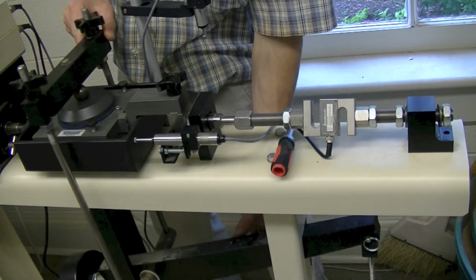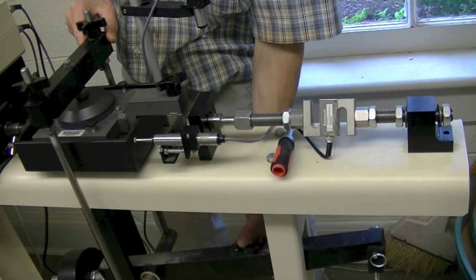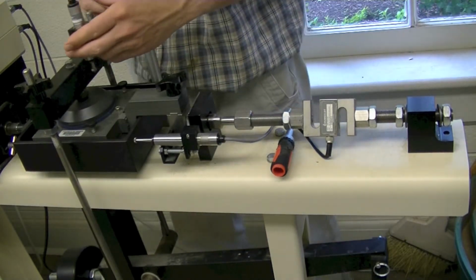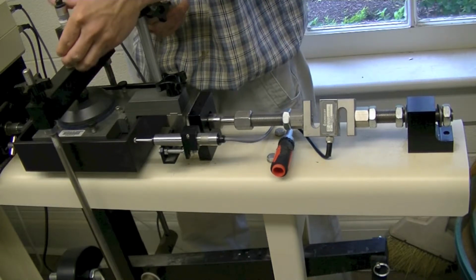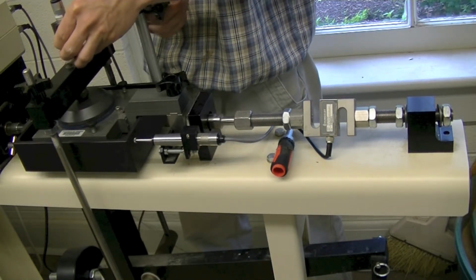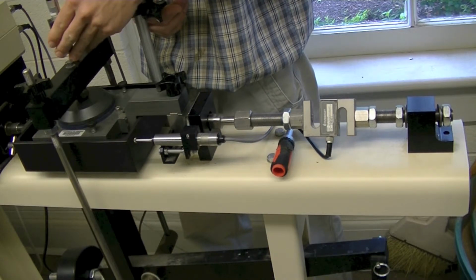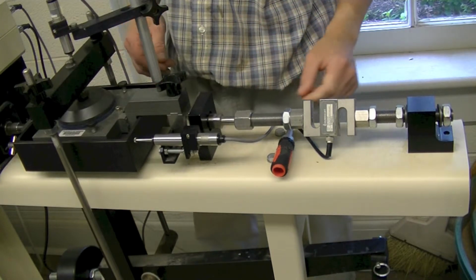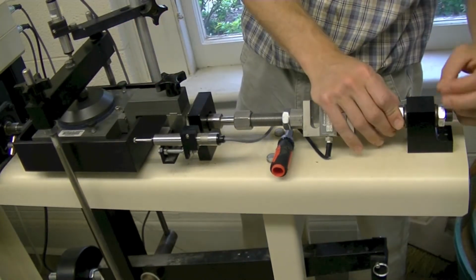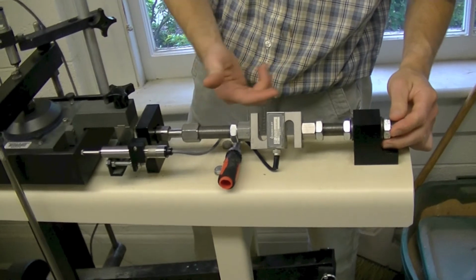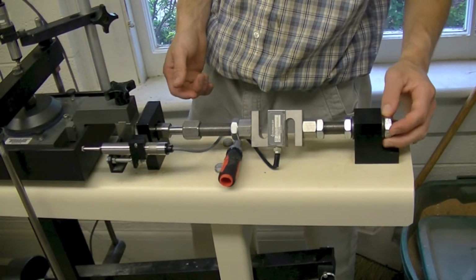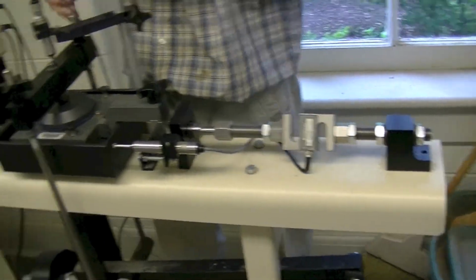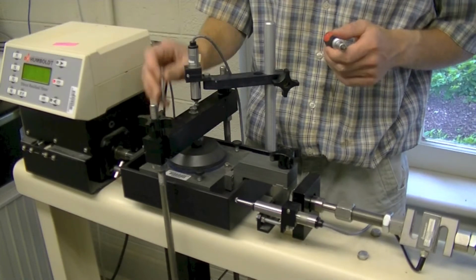Swing the vertical load beam assembly to rest on the ball. Adjust the carriage to rest evenly on the ball by using the nuts beneath and wing nuts on either side of the beam if necessary. Swing the vertical LVDT over so that the tip rests on the beam. Also ensure that the horizontal LVDT tip is touching the side of the box to measure horizontal deformations. Tighten the two nuts on either side of the abutment at the end of the transducer arm. This secures the arm so that force measurements will be output by the transducer. So make sure the nuts are snug.